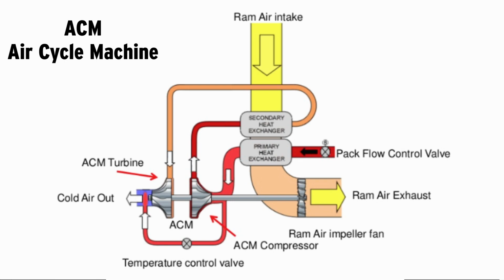It's in a closed system, and it's going to head into a compressor. So we've taken some heat out of it, and now we're actually going to heat it back up again because we're going to compress it further into the compressor. The compressor of the pack is going to compress the air further. It's going to impart more energy to it, and then it's going to run it up and around through another heat exchanger. It's going to lose some more heat. It's at a higher pressure. It's going to lose some more heat, and it's going to go into the turbine of that compressor.